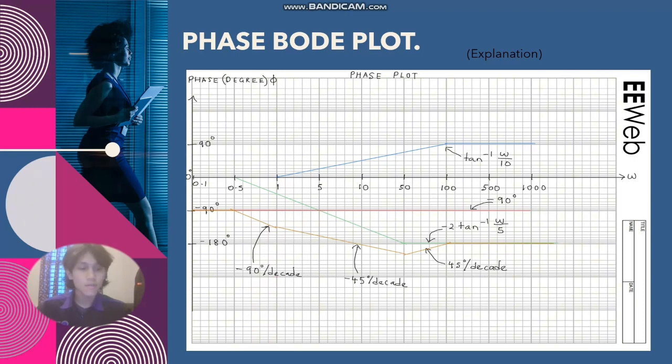A typical goal for phase margin is to have at least 45 degrees, and a higher value might be desirable in more critical applications. In addition to safety considerations, performance is also affected by values that can be determined from both plots. For example, a higher 0 dB crossover frequency usually means a faster response, and higher frequencies mean better noise immunity and lower output ripple.